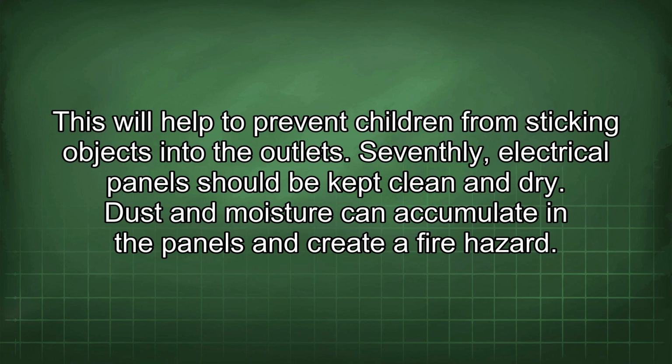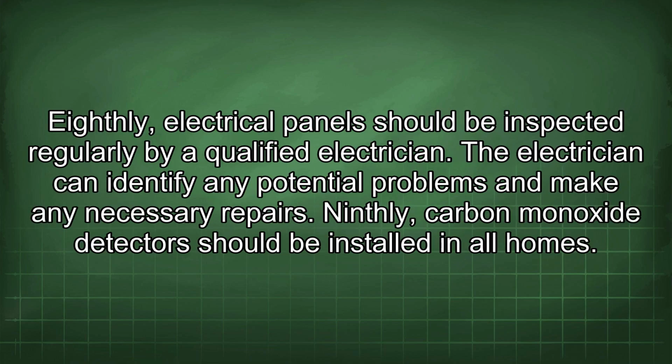Seventhly, electrical panels should be kept clean and dry. Dust and moisture can accumulate in the panels and create a fire hazard. Eighthly, electrical panels should be inspected regularly by a qualified electrician. The electrician can identify any potential problems and make any necessary repairs.